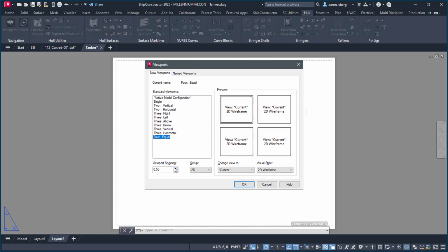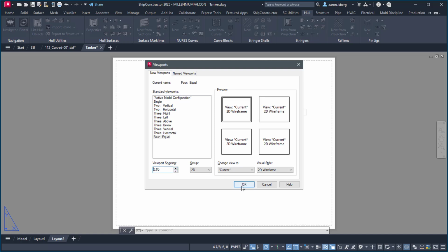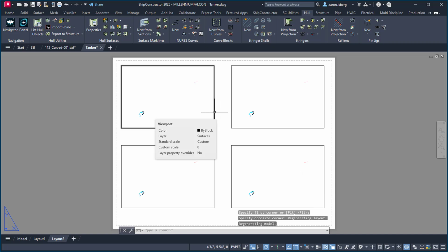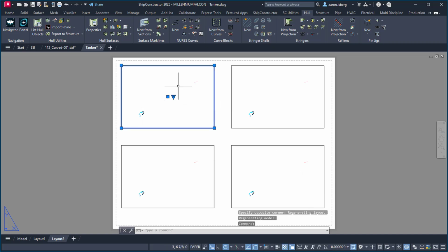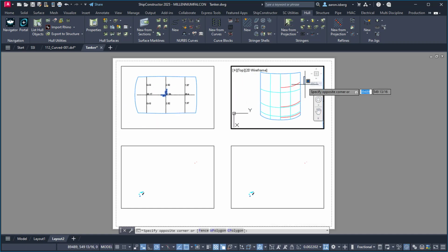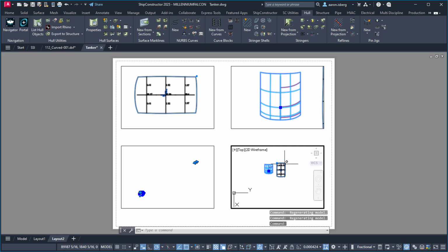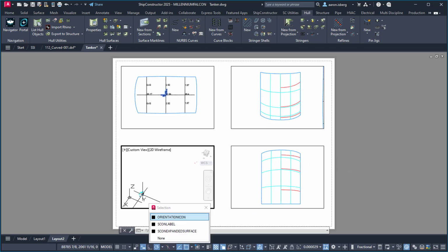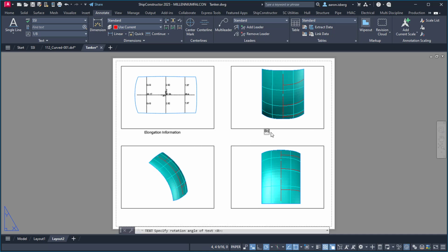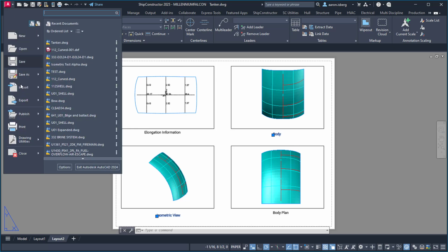Within the Layout tab within the hull drawing, create 4 viewports, selecting the model space for each, and then orientating the views to align in 3 of the viewports, and a perspective projection in the 4th to provide the necessary details required to obtain the overall shapes. From the AutoCAD menu, or using the plot command, export this layout view as a PDF.